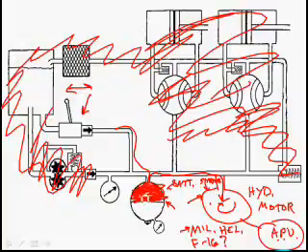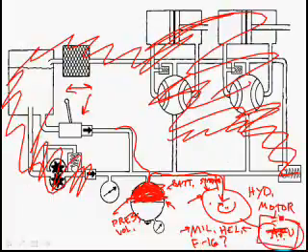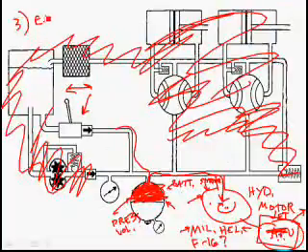Here, we're going to store hydraulic power because we have pressure and we have volume. We're going to convert that hydraulic power into rotating energy. That rotating energy, kinetic energy, can fire up the APU. Then on these military helicopters, the APU is used to start the main engine. On an F-16, instead of starting an APU, it literally starts a little tiny jet engine, and this jet engine is geared into the main engine. And that starts the main engine on the F-16. In either case, number 3, you can use it for engine starts.